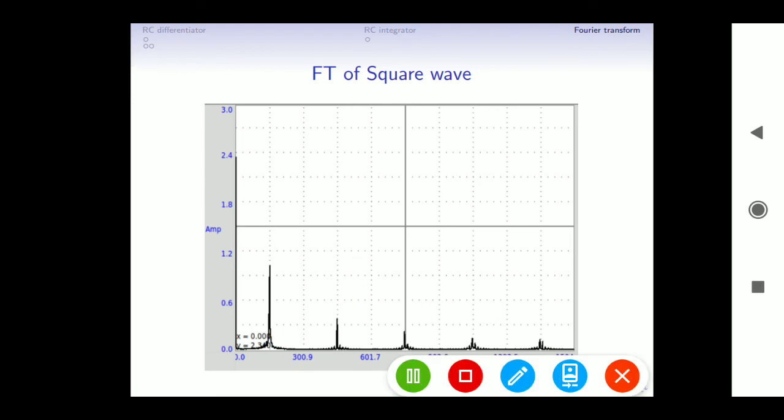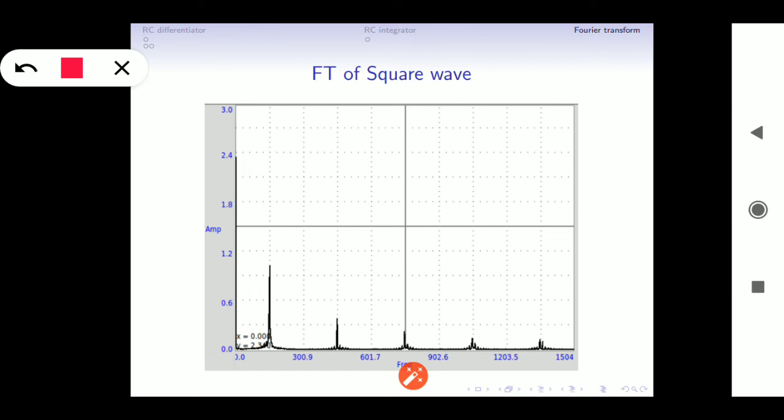And in addition to that, you get a certain signal here. That signal is exactly at 0 Hz. So that's actually the DC component of the square wave. So you get a DC signal as well as AC signal. You get a DC signal because the square wave is shifted above 0. Therefore, you get a DC signal like that. That's a very important thing you should know.